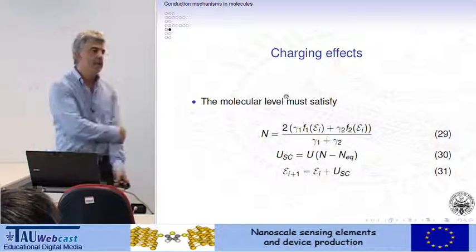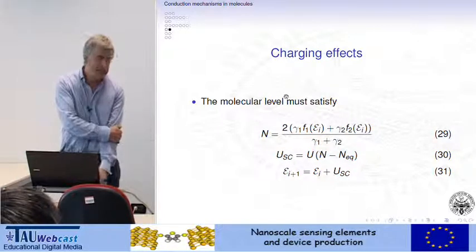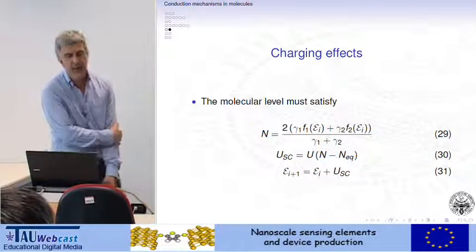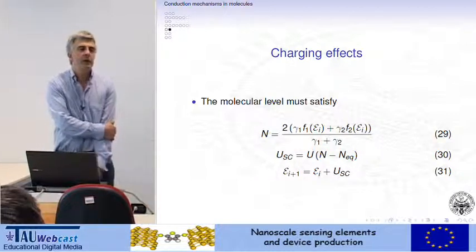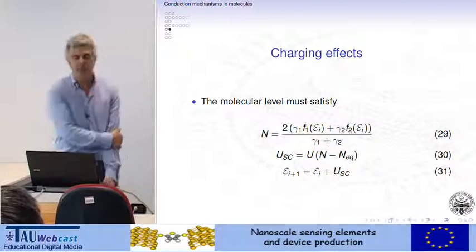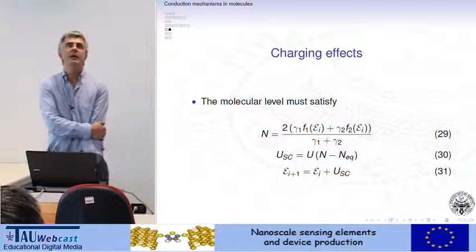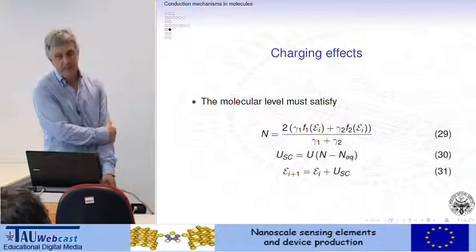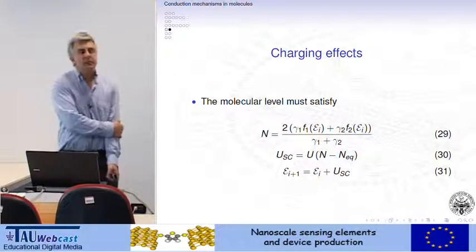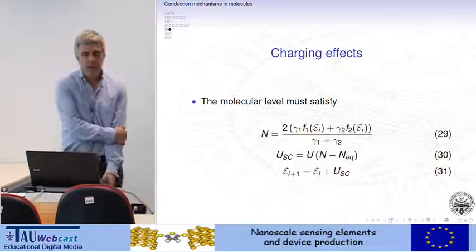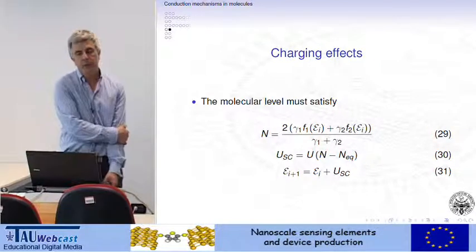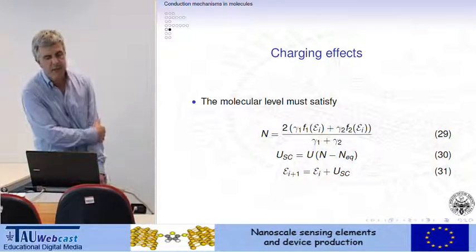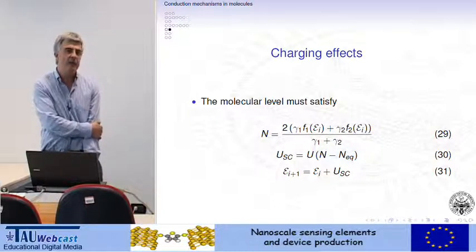The charging effect is important because in the next classes you will see how a molecular system can be described also in terms of Coulomb blockade, because this is a typical effect that modifies the IV curves in nanosystems. The general question is whether, on a molecular device like the one that we studied now, Coulomb blockade can be observed. The answer depends on the interfaces.